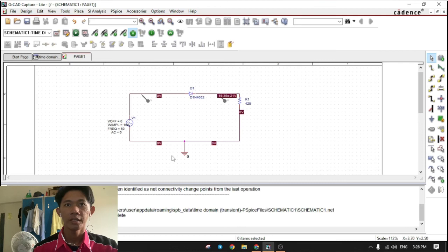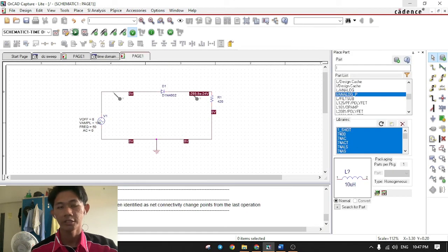And then I put the voltage level marker at the node as shown in figure 6, which is in the middle, behind diode D1. Okay, so I run the simulation, and you will see the graph we get from that circuit.